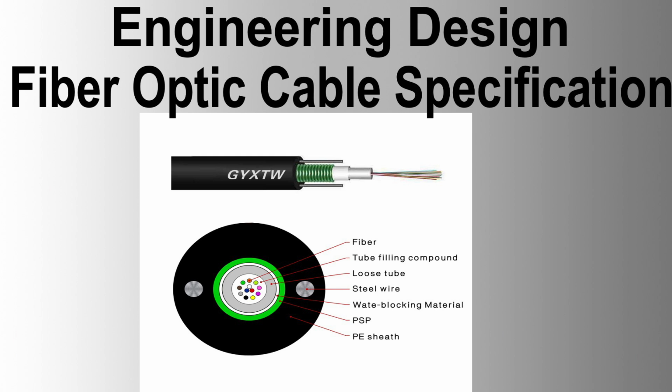Dimensional test. Vendor responsibility. The vendor shall carry out tests on incoming goods to verify the integrity of the materials manufactured. Tube dimension. Measurements for inner and outer diameters with a tolerance of ±10%. Sheath thickness. Nominal and average measurements with a tolerance of ±10%. Outer diameter. Minimum and nominal measurements with a tolerance of +10%. Frequency. Dimensions shall also be tested randomly on one cable length during the manufacturing process.